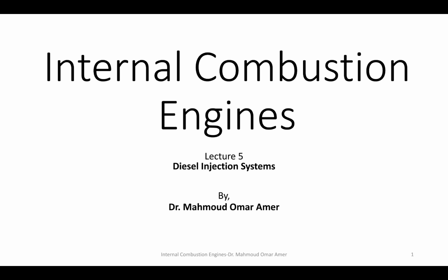Till the previous lecture, we were talking about diesel engines, direct injection and indirect injection. We understood the difference between both of them, and we learned that in order to enhance or improve the mixing between the diesel and the air, we can do two things, either from the air side or from the fuel side. From the air side is to increase the swirl as much as possible, which is limited in direct injection engines. So in direct injection engines, we rely on the fuel.